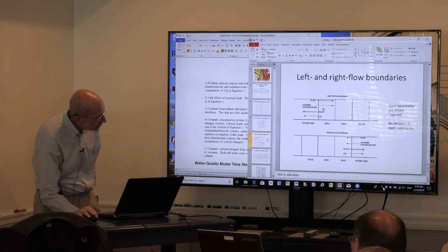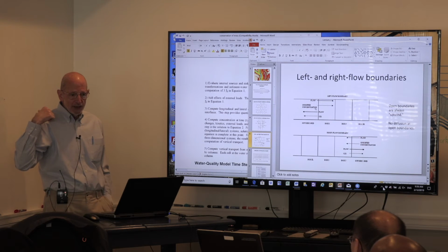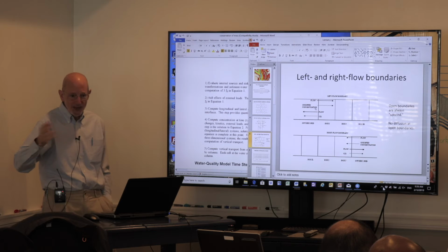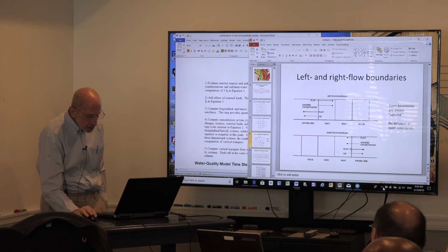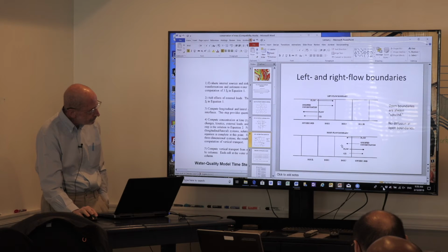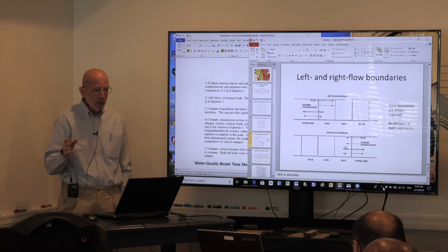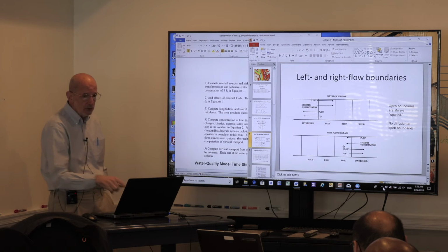You have a similar situation. So this is an upstream boundary, a river, something like that. The other end, you could have a boundary where things flow out, the ocean. It could go both ways, in fact, but you can have an outflow boundary. And when we get to an outflow boundary, so this is our grid, and this is outside the grid, once again the outflow boundaries are hardwired, they're upwind. What flows across that face is the concentration in that cell.